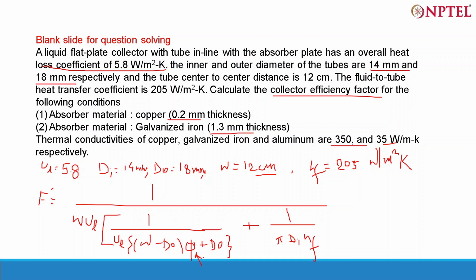So how can you get the phi? There is a formula for phi also: tanh(m (W minus d_o)/2) divided by m (W minus d_o)/2.